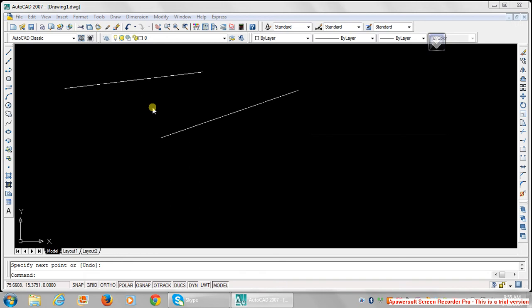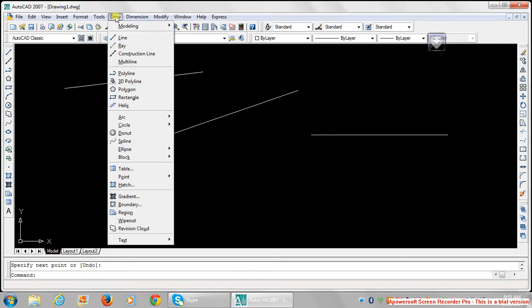If you want to draw a polyline, when you get to the draw menu, click on the draw menu, and you're going to see this is a line, whereas this is a polyline. So a polyline contains multiple lines in other forms, whereas a line is just a straight line. When you're working on them in detail in AutoCAD, you see there is a basic difference. You can make some shapes using line that you could also make using polyline, but there are major differences when you're working on it in advanced forms in AutoCAD.